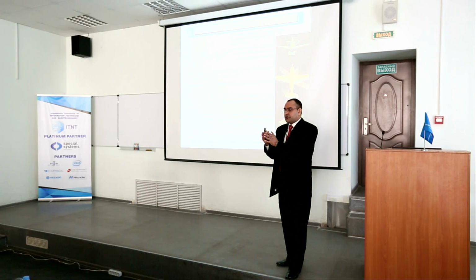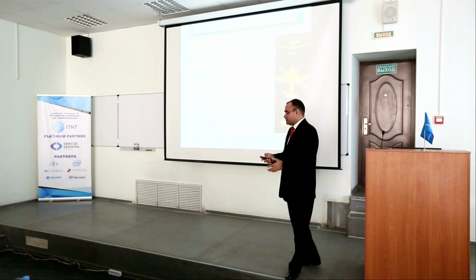As I told you, the system is not as easy as I am telling you. There are a lot of problems and errors in the photographs, like those due to the curvature of the earth, the moving of the earth, sun angle, and lens distortions. So the photograph is not accurate to what we are looking at on the ground.